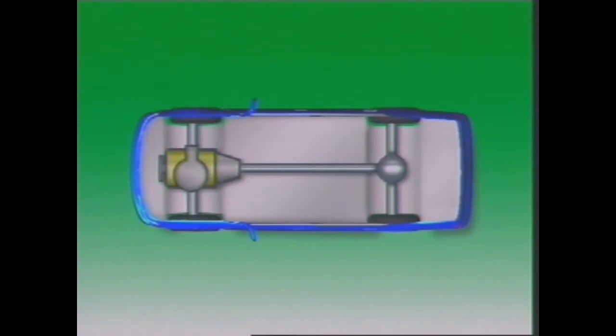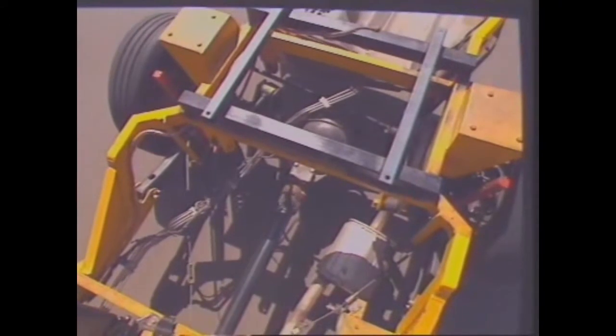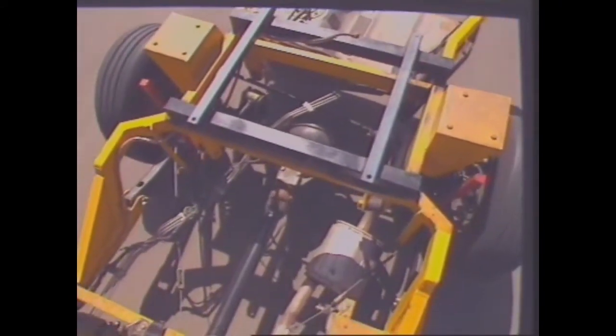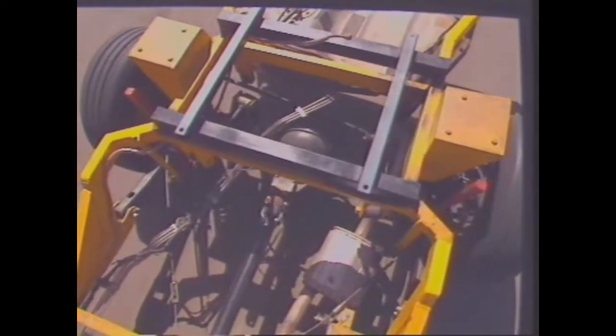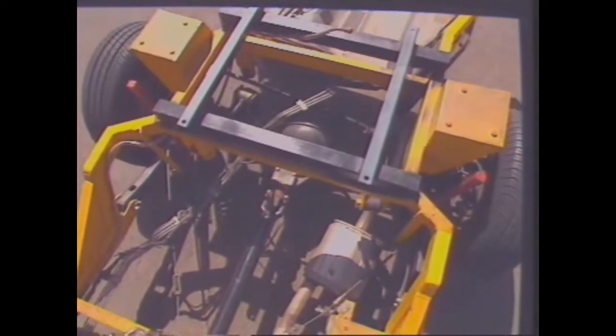Rear-wheel drive vehicles can use a conventional layout with the engine at the front of the vehicle. The torque from the engine is transmitted to the rear-mounted driving axle by propeller, or drive shaft. This spreads the weight of components throughout the vehicle.